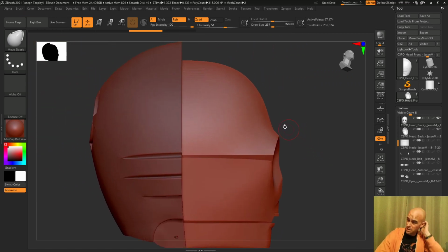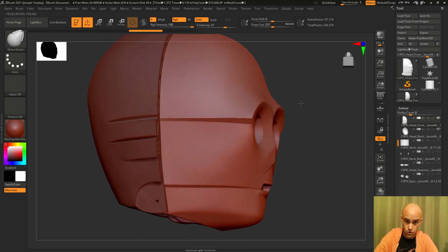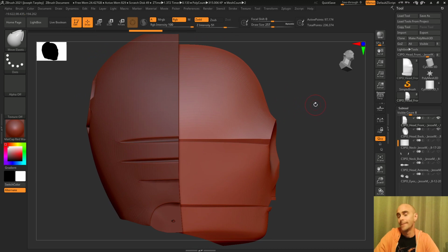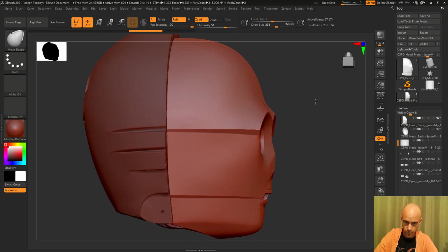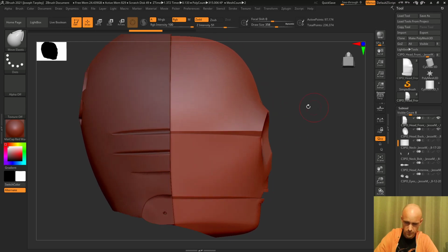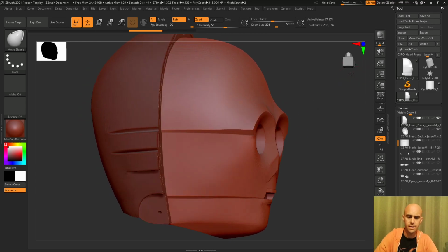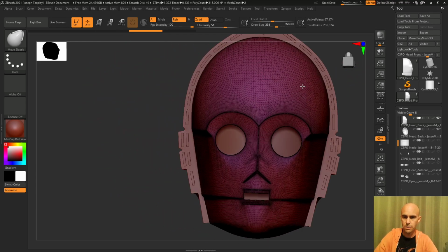So sometimes this happens if you're exporting from one program to another. The way it exports OBJ files or sometimes even STL files, it makes a bunch of triangles instead of a bunch of quads. It's a bunch of 3D nerdy stuff. But we could probably remesh this thing. ZRemesher. Let me look here.